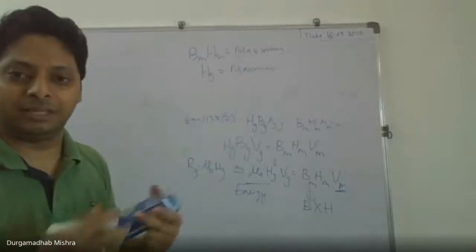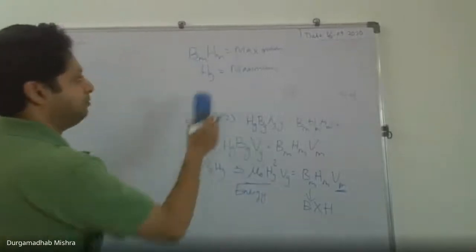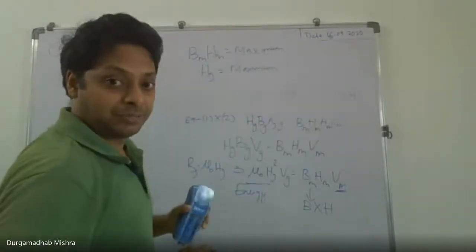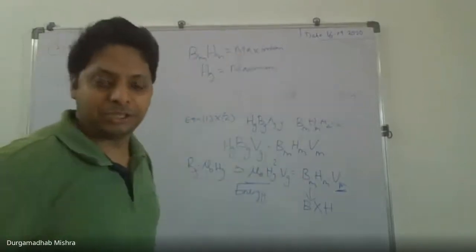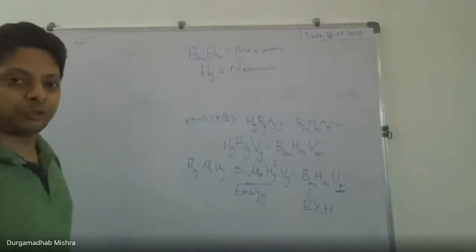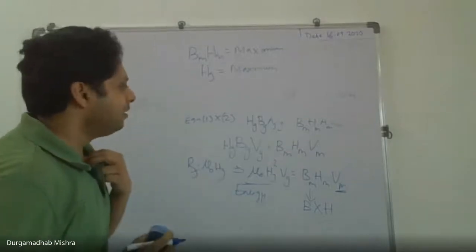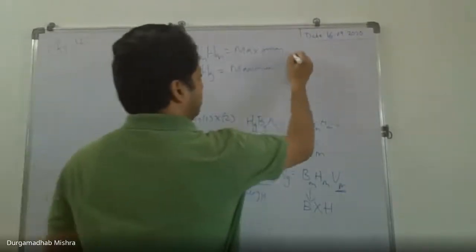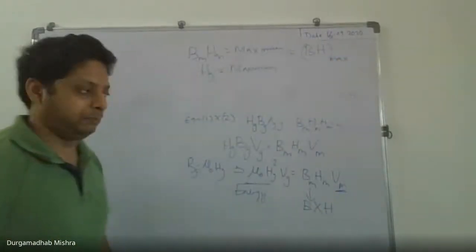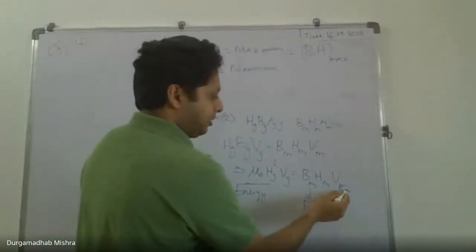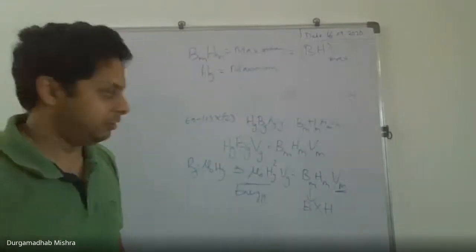That is how we can get as much field or magnetic induction from the permanent magnet. That means we have to operate the magnet when the product of B and H is maximum, and that's why we have BH max as a figure of merit. This is where the BH max concept comes from. Another thing is, look at this Vm: we said we have a constant volume Vm.